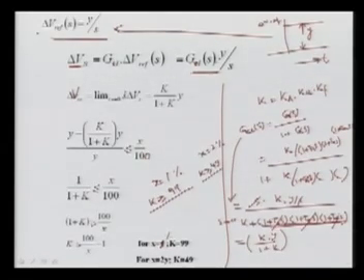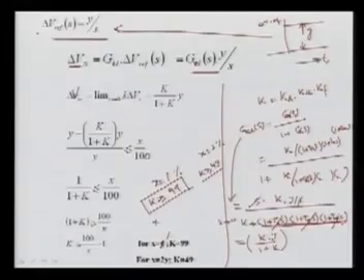This shows that if you want more accuracy, your gain must be larger. You have to go for the larger gain. For example, if you are using x equal to 0.1%, what will be this value? Putting 0.1 here, 1000 minus 1, so k must be greater than 999. So for more accuracy, gain must be larger.